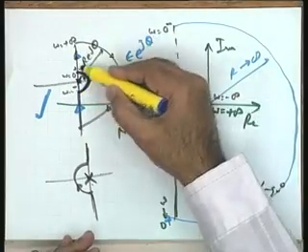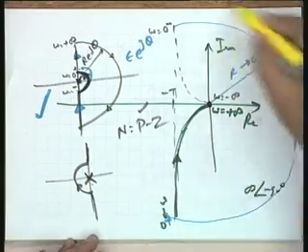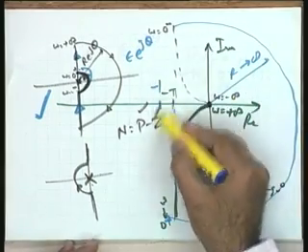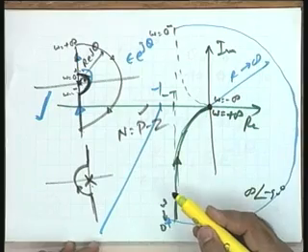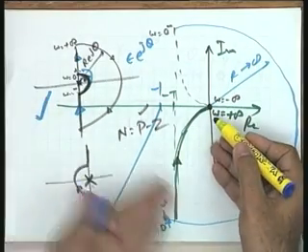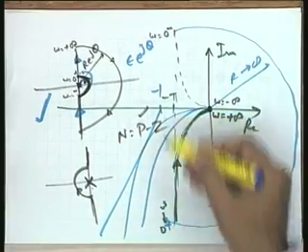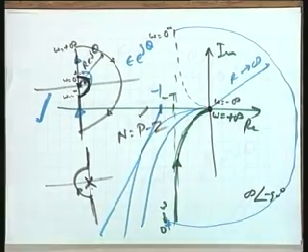And now this has been modeled as this infinite semicircle, and therefore if you take the minus 1 point, the plot does not cut there. For all values of k, as you keep on changing the value of k, only the magnitude will change, but it will still not pass through the minus 1 point.